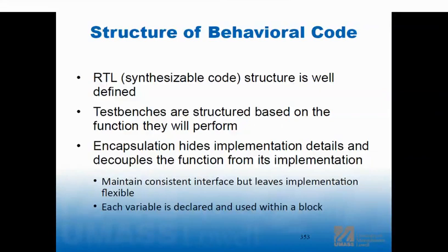That if you had something that gave you high-level constructs that you could write that would generate RTL for you, it doesn't really. People think they exist. They think they're selling them to you, but they don't. You can buy a UART, you can buy a SPI interface and latch them all together. But if you want a state machine, you're taking the construct that I gave you, or maybe something that will allow you to graphically input to it. So take advantage of the kinds of things that UVM would do, right? Consistent interfaces, a consistent kind of hierarchy.